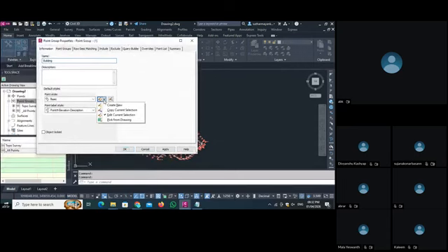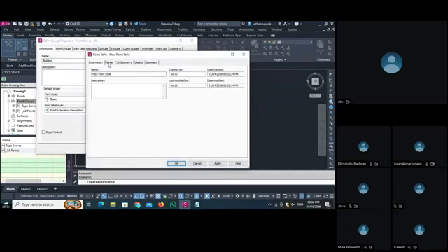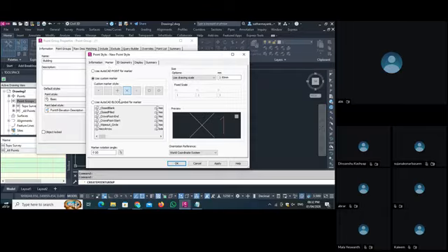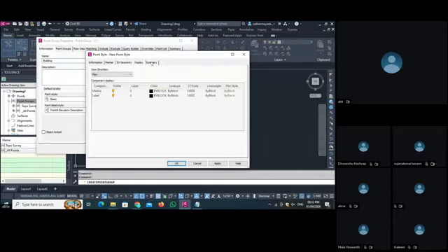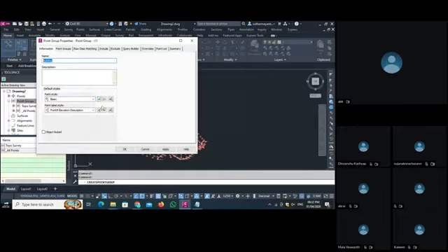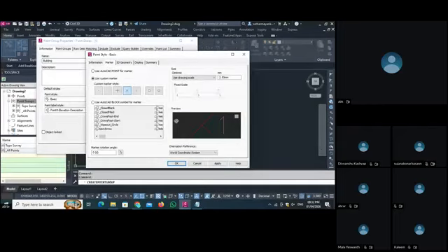Okay, so you can create your new point style from here. You can give that point style a name. You can provide a marker to it. You can change the shape, all the things, and you click Apply and OK. You can create your own point style. Also, you can edit the current style. See here, our existing style is using a cross.